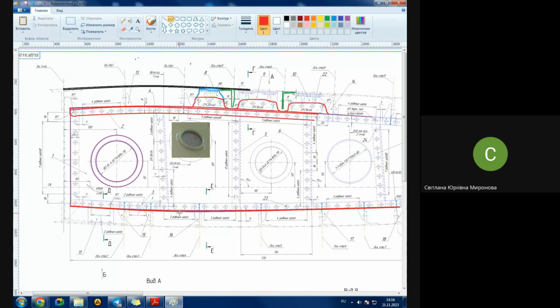This place. There are two most important sizes that you're responsible for during assembly. Of course, you're responsible for each particular single rivet also and its quality. But in general, when we talk about accuracy, the first thing is to provide the distance between this top line and bottom line, not the whole contour even, but this theoretical outline of the rib at the top and theoretical outline of the rib at the bottom. Let's take this idea in our mind first.